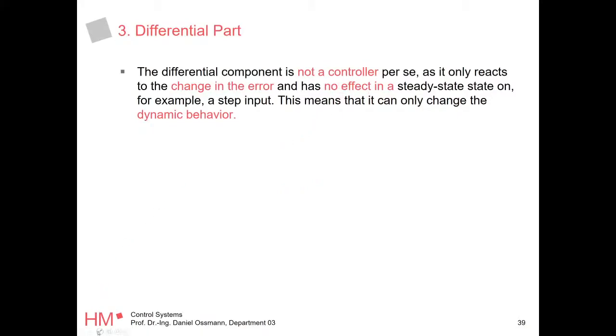Remember, when we say in steady state, we always think of a step input, right? So your u of t is this. If you run that through a D or DT1 system, this actually kind of looks like this. So in steady state, you could write here e and here u of t, this guy gets zero because it's differentiating.